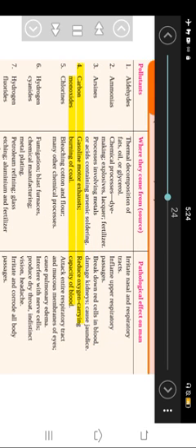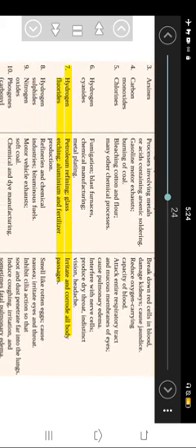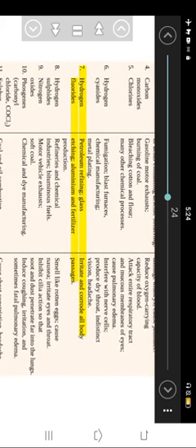4. Carbon monoxide, from gasoline motor exhausts and burning of coal, reduces the oxygen carrying capacity of blood. 5. Chlorine, from bleaching cotton and flour and many other chemical processes, attacks the entire respiratory tract and mucous membranes of eyes, and causes pulmonary edema. 6. Hydrogen cyanide, from fumigation, blast furnaces, chemical manufacturing, metal plating, interferes with nerve cells, produces dry throat, indistinct vision, headache. 7. Hydrogen fluorides, from petroleum refining, glass etching, aluminium and fertilizer production, irritate and corrode all body passages. 8. Hydrogen sulfide, from refineries and chemical industries, bituminous fuels, smells like rotten eggs, causes nausea, irritates eyes and throat.